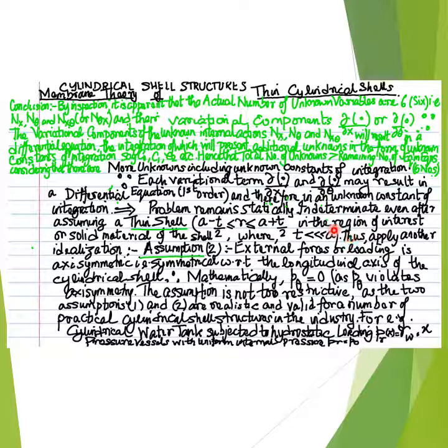Intuitively, one can interpret or conclude that the membrane solution, that is the solution of the unknown internal in-plane or membrane actions, will require another simplifying assumption in addition to the earlier implemented thin shell assumption.